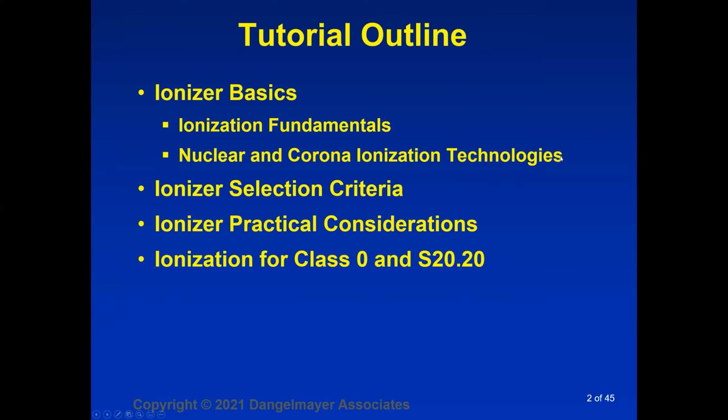There we go. So our webinar tutorial today will cover some ionizer basics. We'll look at ionizer fundamentals, and we'll look at the nuclear and corona ionization technologies. We'll run through some ionizer selection criteria, how you choose an ionizer for a particular application. We'll talk about some practical considerations in the selections of ionizers. And we'll talk about ionization for class 0 and what the industry standard ESD control program document, S20.20, says about ionizers as well.